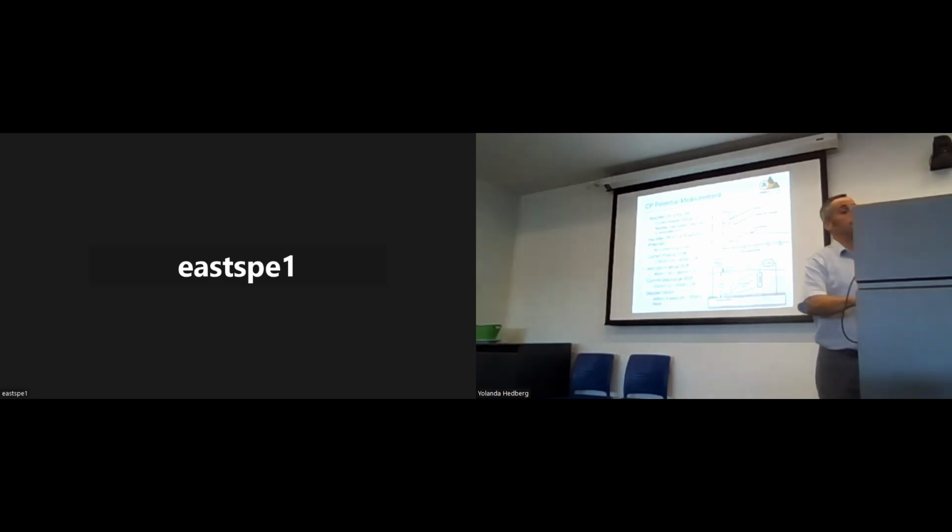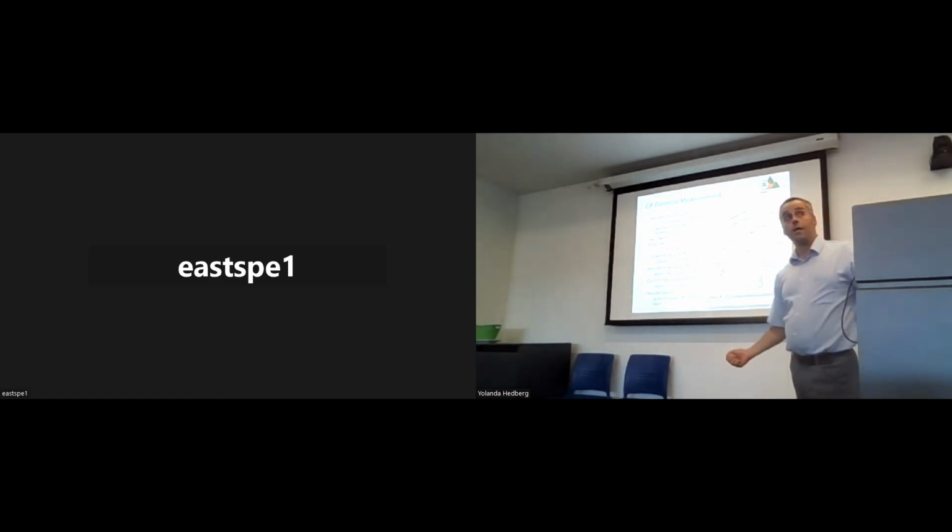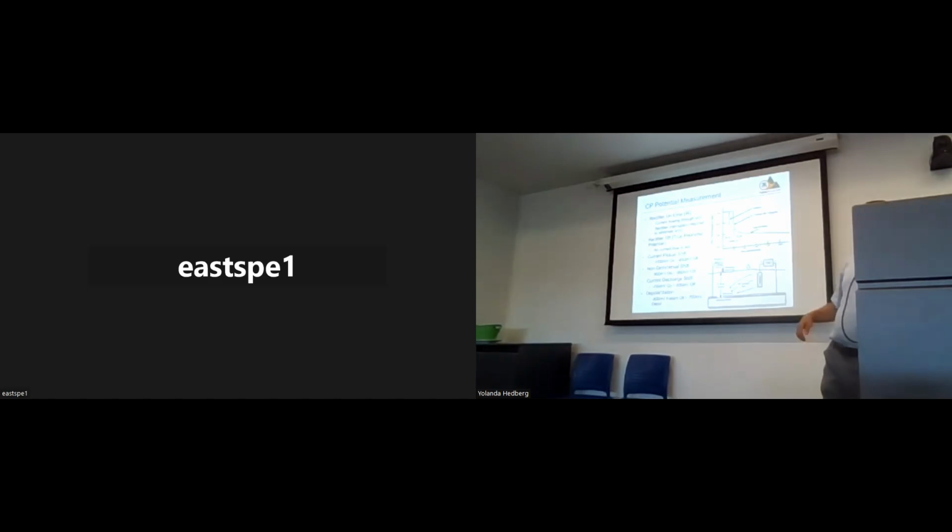Now, if we have that same reverse shift scenario, negative 700 millivolts on, negative 800 millivolts off, more current is flowing away from my pipe than going to it. The difference is now I'm not meeting cathodic protection criterion.